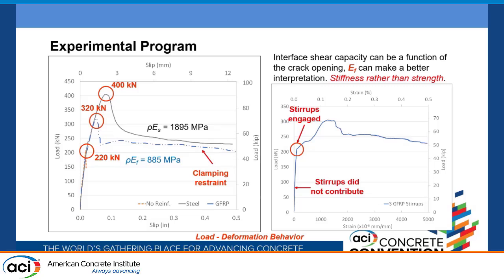The other thing is, and I'm not a designer, so I'm probably off here, but I'm not sure what phenomenon we're trying to focus on, because if it's a shear crack, there's going to be an opening that is opening with a different amount through the line. If you're talking about dowel, it's two materials, and so you should consider the effect of the two materials. But even more importantly, why are we looking at the elastic modulus and not at the shear modulus? So why are we looking at a comparison of the elastic modulus times rho when it's a matter of shear?